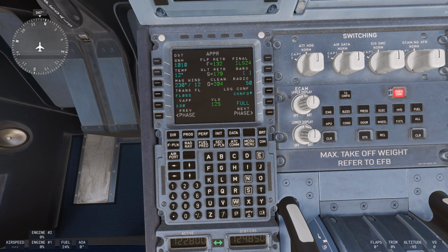Now the last section is our landing configuration, flaps and speed brakes. So this just refers to the flap settings used for landing. This is important, fairly obvious. Different landing configurations affect approach speeds and landing distances. A config full flaps provides the lowest approach speeds and the shortest landing distance, and this is used for short runways and wet conditions. It does mean more drag and higher fuel burn, slower approach speeds.